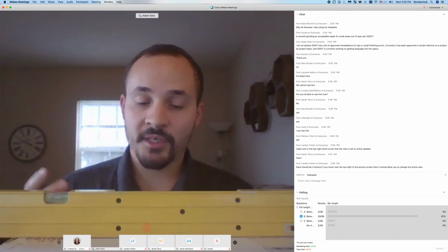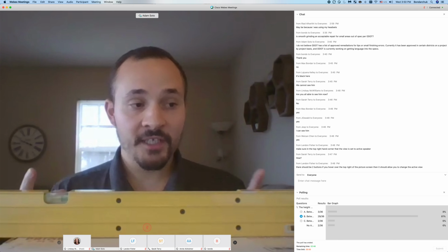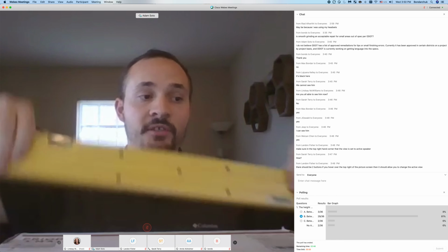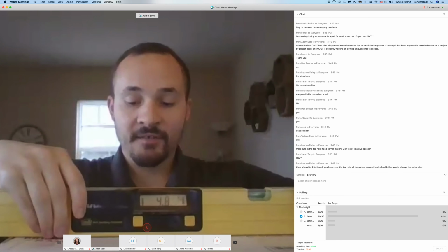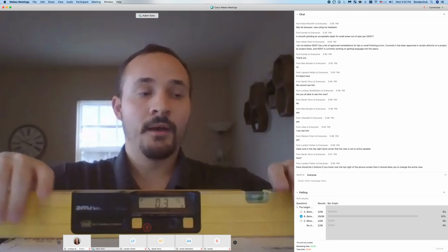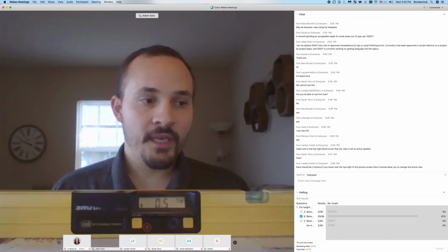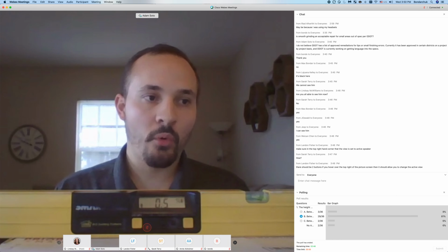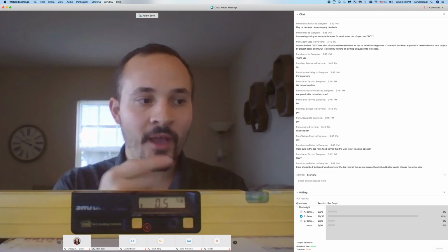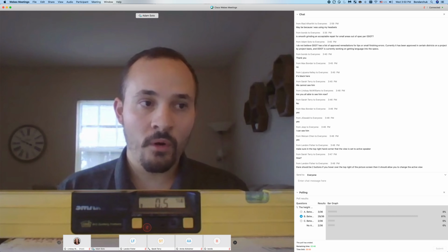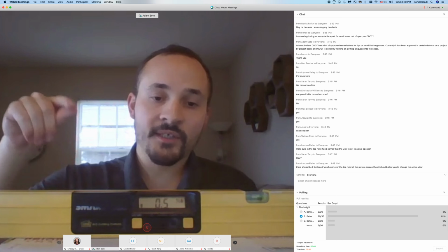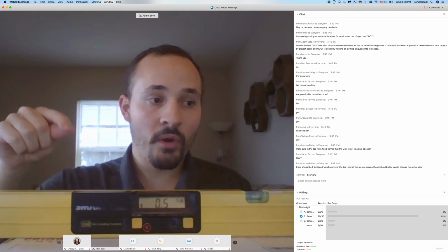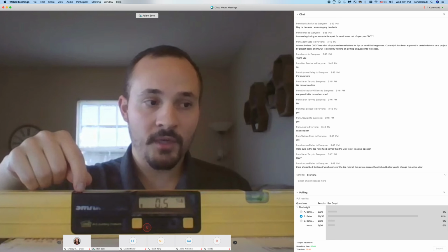If you finish the calibration steps and the level is not reading the same way when you flip it 180 degrees, then the level is calibrated incorrectly. Generally, we accept the level as calibrated if it's within 0.1% of itself. So if it read 0.5 that way, and I flipped it and it read 0.4, I would have started the inspection anyways. And with that, we're accepting that the level might be up to 0.1% off from true.